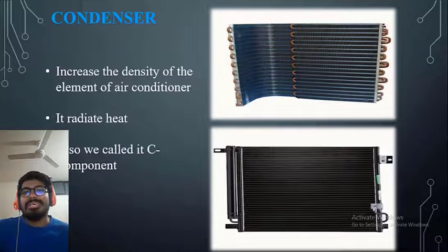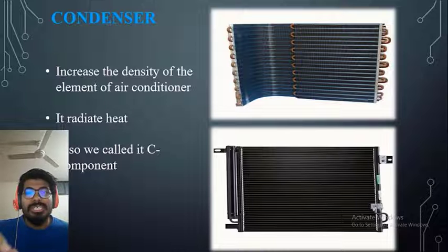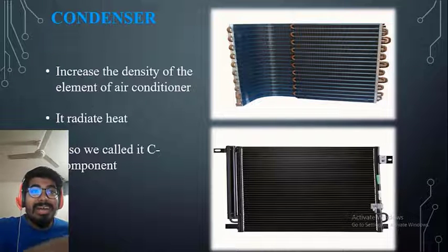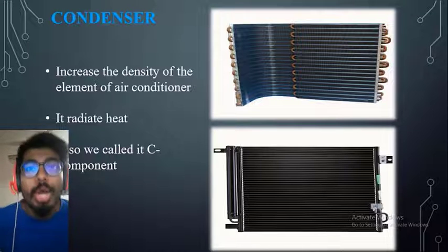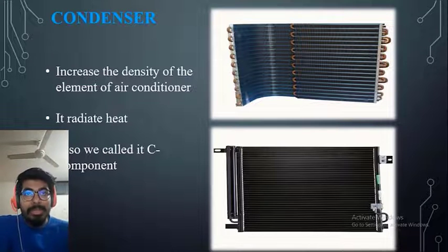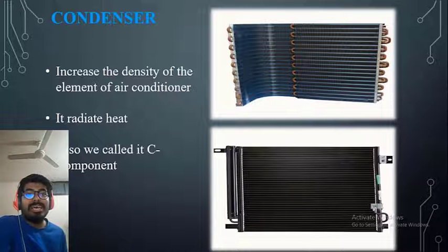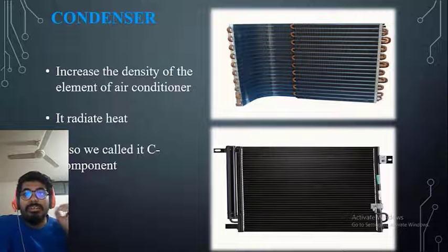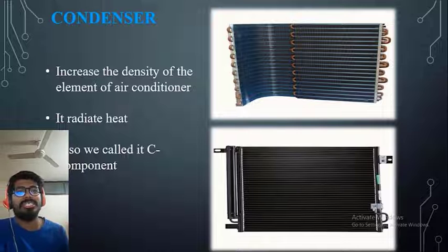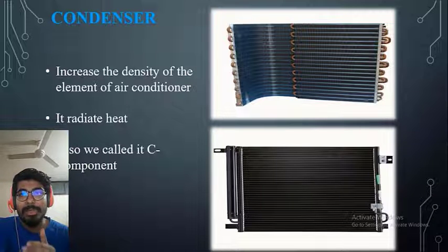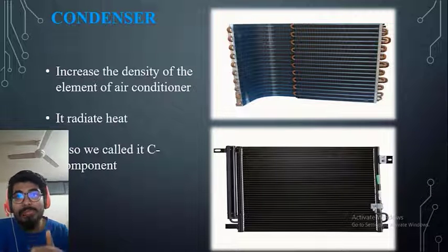A condenser is the outdoor portion of an air conditioner or heat pump that either releases or collects heat depending on the time of the year. The condenser coil receives the hot pressurized gaseous refrigerant from the compressor. Then the condenser coil is designed to release the heat the refrigerant is carrying outside. This cools the refrigerant down and turns it back into a liquid ready to absorb more heat from our home.